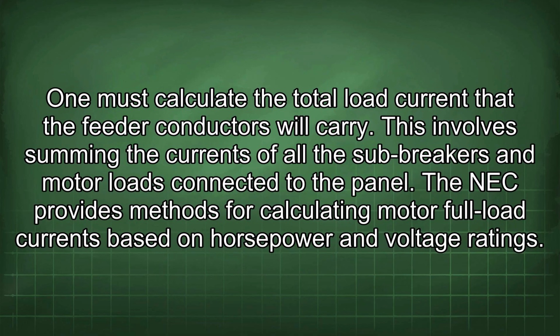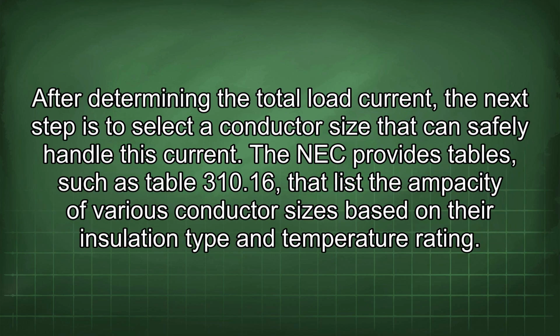One must calculate the total load current that the feeder conductors will carry. This involves summing the currents of all the sub-breakers and motor loads connected to the panel. The NEC provides methods for calculating motor full load currents based on horsepower and voltage ratings. After determining the total load current, the next step is to select a conductor size that can safely handle this